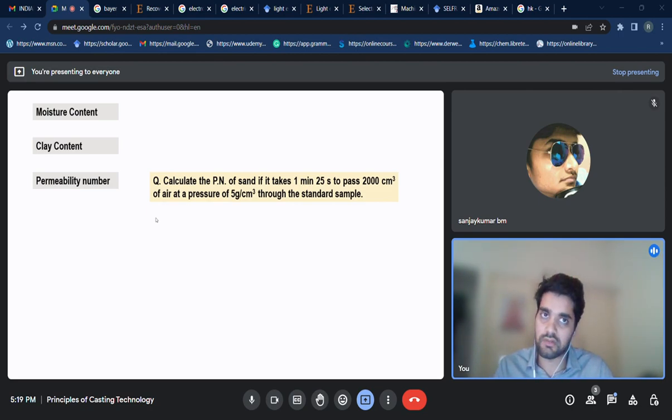So this is how the moisture content is determined. In lab scale also, when environmental engineers go to the landfill and collect their samples from there, the first thing after the sample collection is to remove the moisture content. We need to calculate the weight loss.